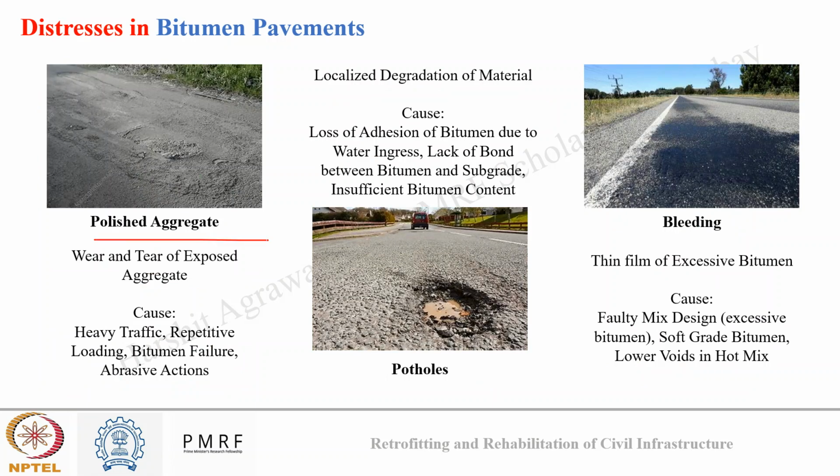Seventh one is polished aggregate, or we can say abrasion cracking. They are basically caused by wear and tear of exposed aggregate, and they occur mainly due to heavy traffic, repetitive loading, and bitumen failure due to abrasive action.